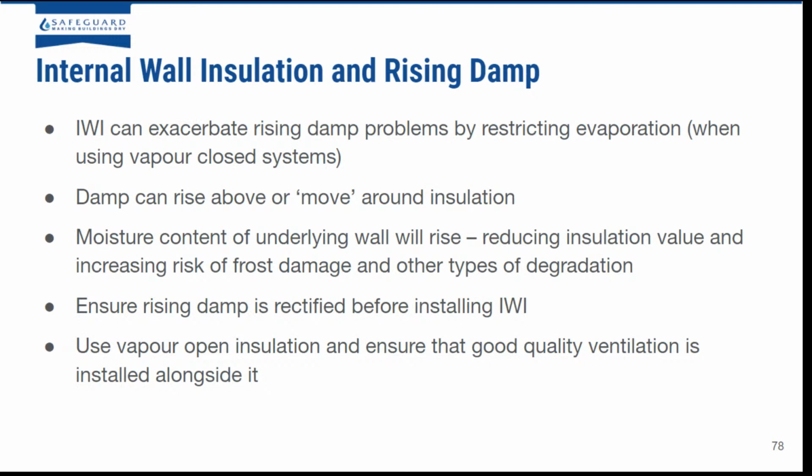Okay, one last thing with IWI. Rising damp can be affected by IWI if you're using a non-vapor open system. Damp can rise above or move around the insulation, and the moisture content of the underlying wall will rise, which will reduce the overall insulation value and increase the risk of frost damage and other types of degradation. So ensure rising damp is rectified before installing IWI, and consider the use of vapor open insulation as well as